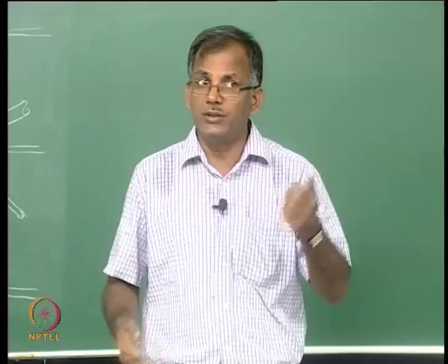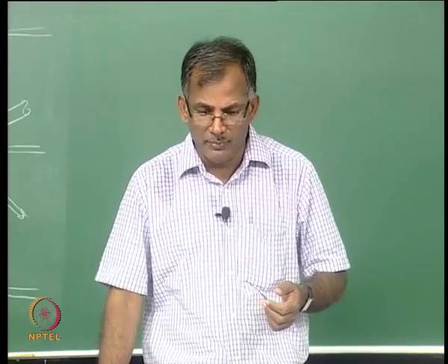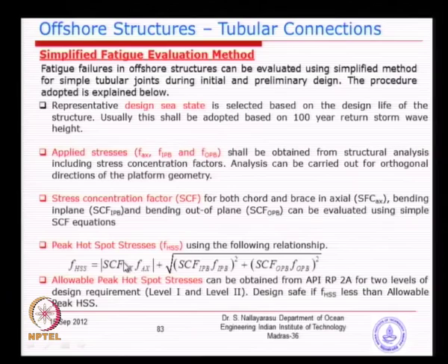So, when we are doing the in-service condition we do exactly the same, except that we will not multiply the stresses by the stress concentration factor. We will be taking only the nominal stress to check the members, whereas here we are going to take the local hotspot stress to check the joints, and then the allowable peak hotspot stress is just a comparison.